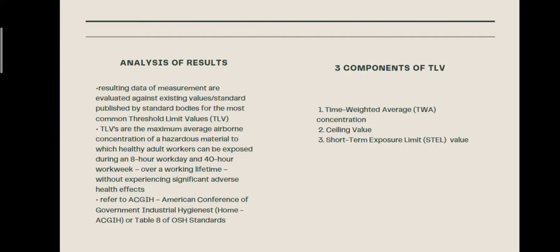TLVs are the maximum average airborne concentration of the hazardous materials to which healthy adult workers can be exposed during an 8-hour workday and 40-hour work week, over a working lifetime, without experiencing significant adverse health effects. We must refer to the ACGIH, or American Conference of Governmental Industrial Hygienists, or Table 8 of OSH standards.